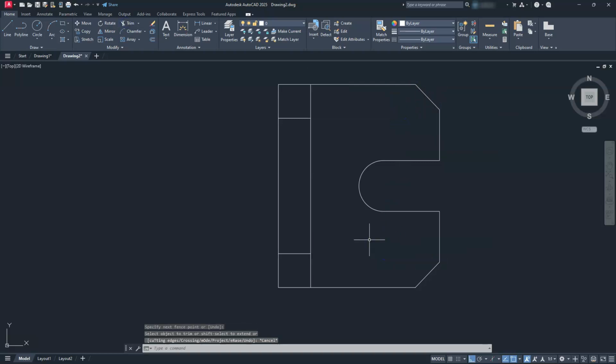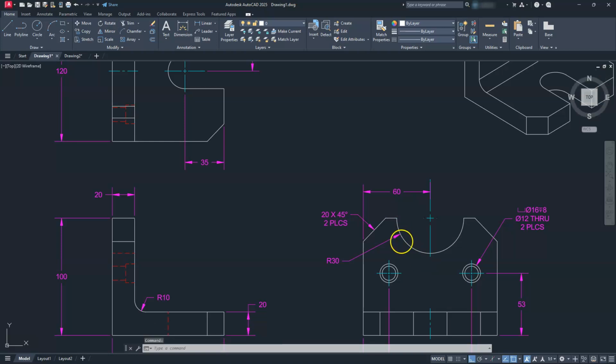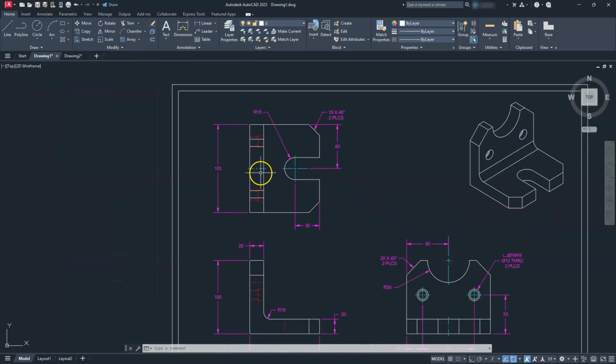Okay. Now we have another surface that is showing up on the inside of here as well. What I'm referring to is that we're going to have this circle part that's going to cut out, right? So it's going to leave a little bitty edge here at the top. So what we have to figure out is how to create that and show that over here, right? So it has a radius of 30. What that means is that from the center out to this distance is going to be 30, and likewise on the other side. So from the center to the edge of this should be 30.